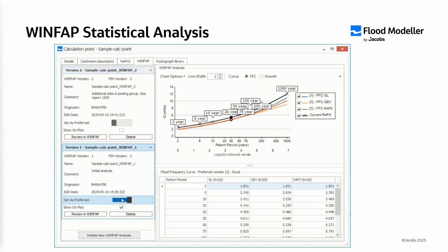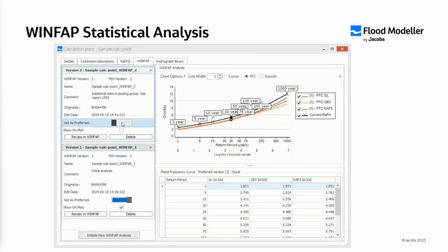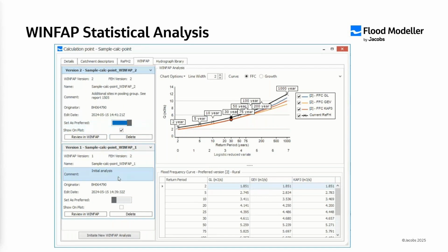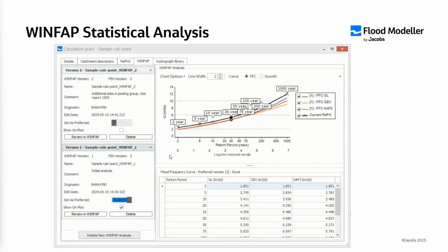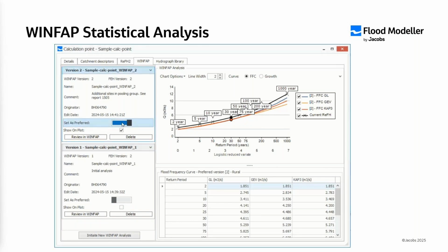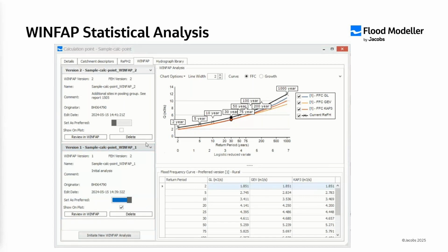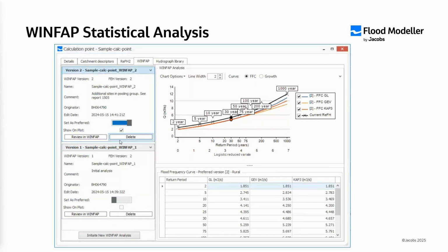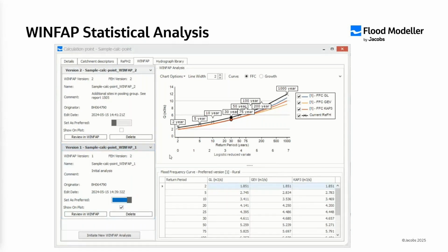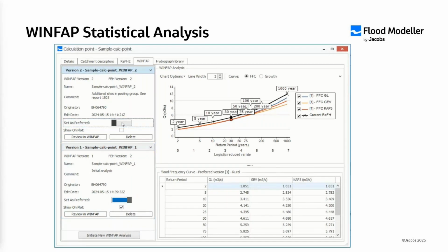This involves selecting relevant gauging stations to form a group that meets the required criteria. For example, having a sufficient number of years of data, the 500 years being the default. I will examine the pooling group for any outliers or inconsistencies. You can conduct a QMED analysis to estimate the peak flow at your site, and you can use observed flow data from the selected pooling group.